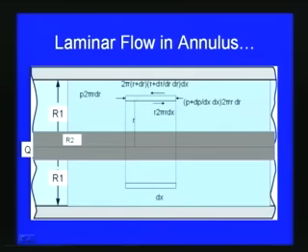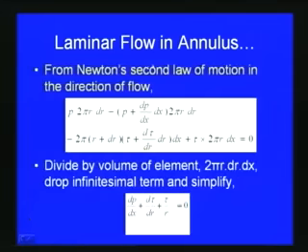So, this is the fluid element which we consider, and the forces acting are the pressure force on both sides of the fluid element, and then the shear force. On this side it is given by tau into 2 pi r dx, and with respect to the incremental other side it is 2 pi into (r plus dr) into (tau plus d tau by dr into dx). Now with respect to this we will be considering Newton's second law to derive the equation.